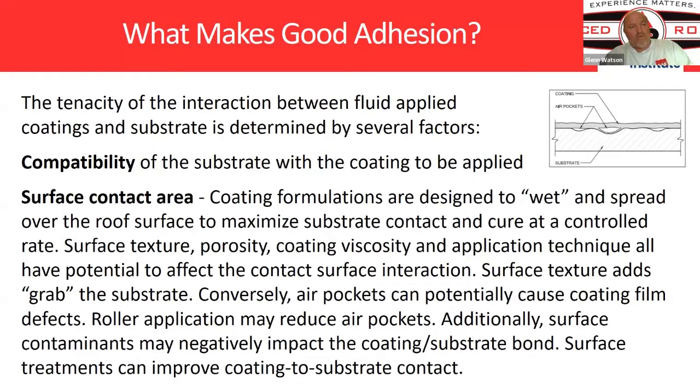You'll get micro voids under a system, like Swiss cheese or craters on the moon. You want even, compressed adhesion, uniform across the layer of product that you're putting down. That's the concept you always want to try to capture. When you're putting a product down, you're not painting, you're applying. That's the mindset you have to have.